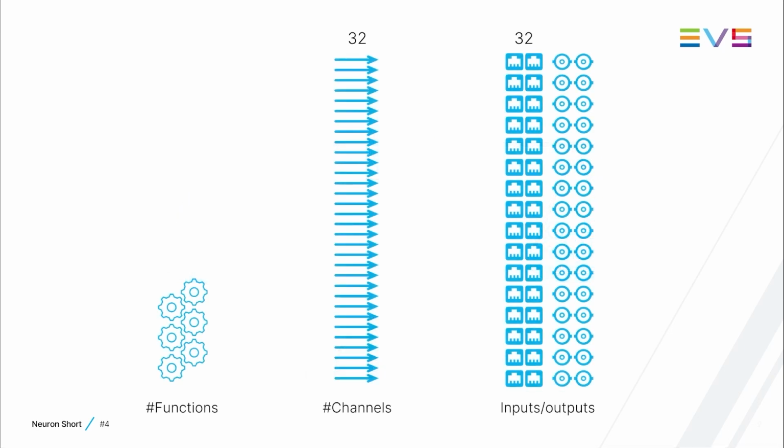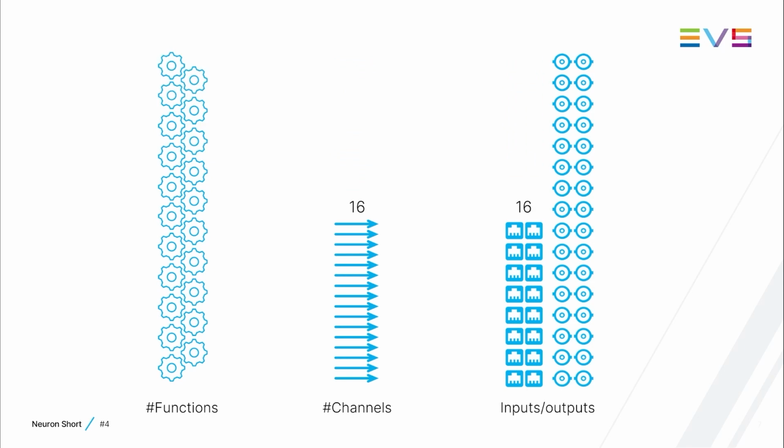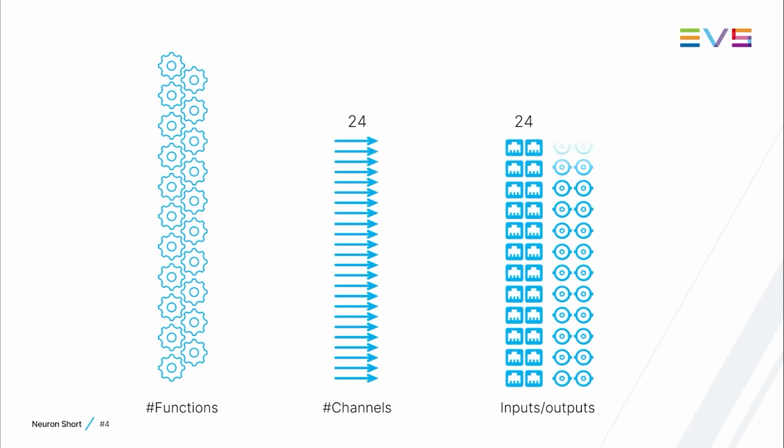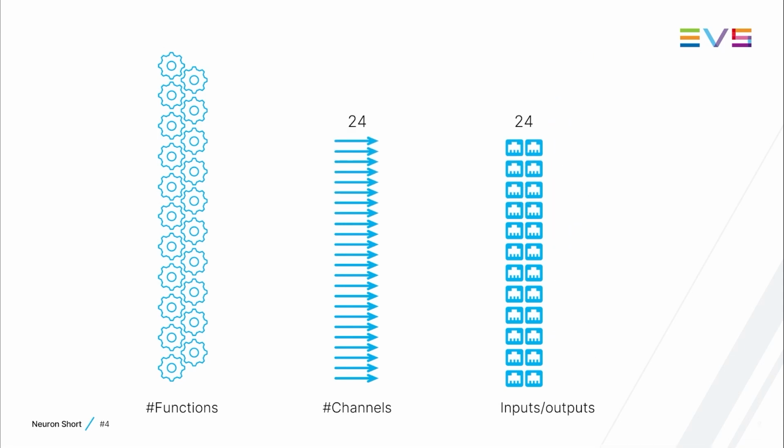Where with the bridge cards we were looking at 32 processing paths, with the ability to bridge 32 Full HD or 8 UHD channels, a convert card typically has 16 processing paths, with the ability to fully process 16 Full HD or 4 UHD channels. We're always expanding our portfolio of software versions, so the 16 processing paths are not set in stone. There's a convert version available with 24 processing paths, for instance, but without the SDI I/O capabilities, since again, it's always a trade-off.